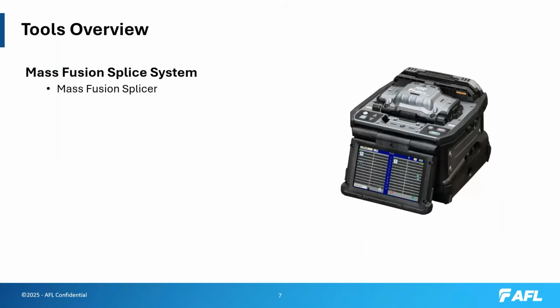They are fixed V-groove, meaning the V-grooves themselves are stationary. So you have to be very much on your P's and Q's from the standpoint of controlling contamination and fiber prep work leading up to the actual splice. Reliable, high-duty systems. They can be used with battery packs. They can be used with generators with no issues.